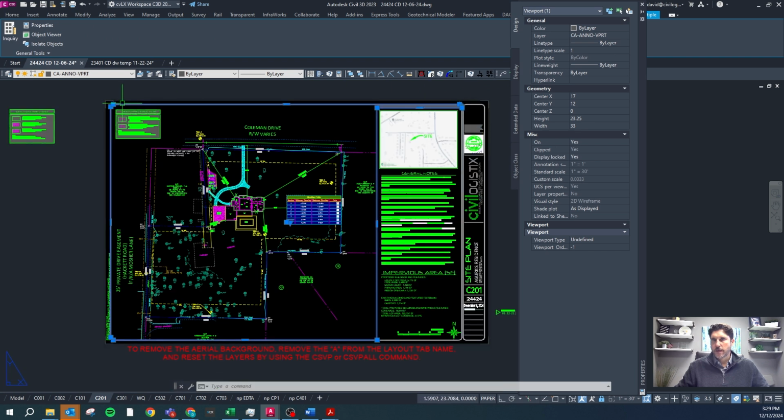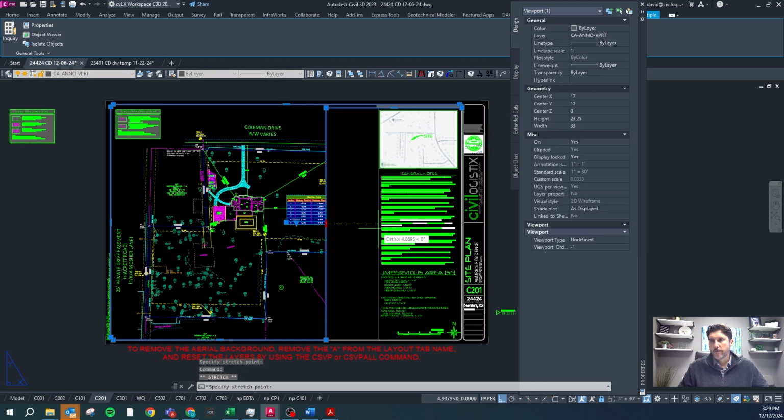This goes all the way to the top and bottom and left and right for a reason, and that's because the methodology by which the command matches, it basically picks the center point of this viewport and puts it at a particular place in model space, and then it applies a certain scale. So if you move this over left and right, it doesn't matter because this boundary here and this boundary here stayed the same. So feel free to move that, but just don't change that.